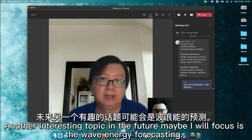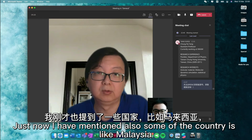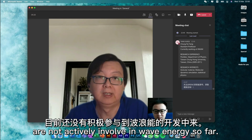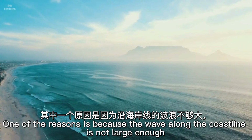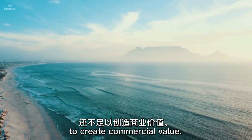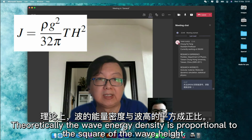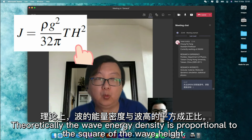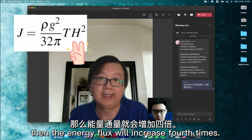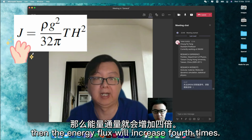Another interesting topic I may focus on in the future is wave energy focusing. Just now I also mentioned that some countries like Malaysia are not actively involved in wave energy so far. One of the reasons is that the waves along the coastline are not large enough to create commercial value. Theoretically, the wave energy density is proportional to the square of the wave height. So that means if we could double the wave height, then the energy flux will increase 4 times.